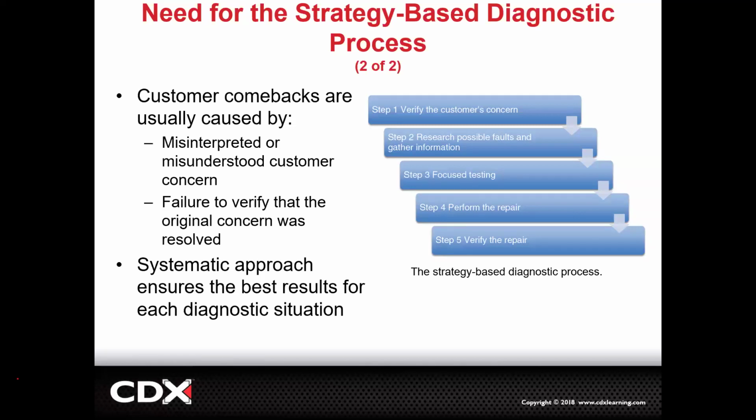The next thing we want to do is research possible faults and gather information. So even me right now, if I get a vehicle in with an AC concern, I'm going to back up a little bit. I may do some basic testing, but a lot of times I'm going to research and gather information. Are there TSBs? Was there any work history performed recently? Another thing I may do that's kind of within the system is, is the compressor running, right? All I got to do is look, is the compressor running? If the compressor is not running, that's taking my mind in one direction. If the compressor is running, but it's blowing warm air, that's taking my mind in a totally different direction.